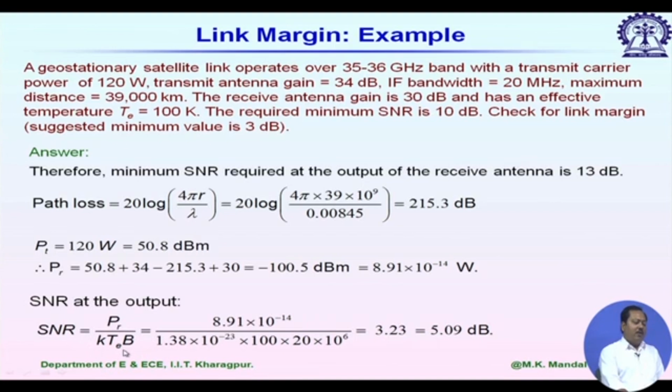We do not have any control over separation distance and IF bandwidth, it depends on the application. So, again we can't decrease the IF bandwidth. So, we have to only play with the transmit antenna gain, receive antenna gain, transmit power, and the receiver temperature.